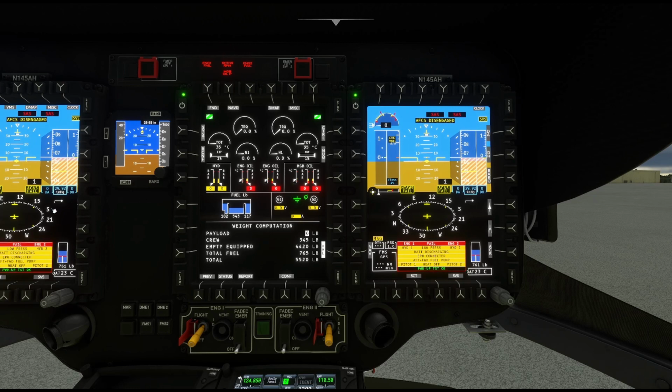We call them multifunctional displays because they can be any of the displays. They can be a flight navigation display, they can be a navigation display, they can be the vehicle management display, they can be a DMAP, they can be the miscellaneous display. So any of that stuff is available on any of the screens. You'll notice right up here it's not available on this screen. In real life, we would have to power down MFD4, and that would provide all of that functionality on MFD2.